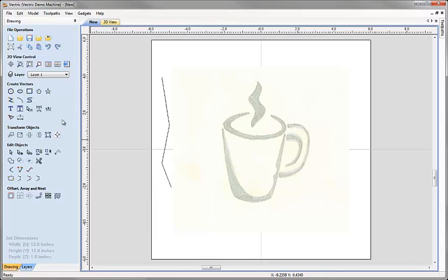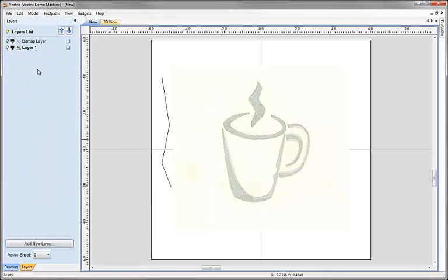So if I hit close now and look at the layer manager, we can see that both the bitmap layer has the data on it and layer 1 does, but if I was to create another new layer, then that will be shown as not having any data on it. So whether this piece of paper here is displaying something on it or is blank is a really nice quick visual indicator as to whether that layer actually contains any data or not.